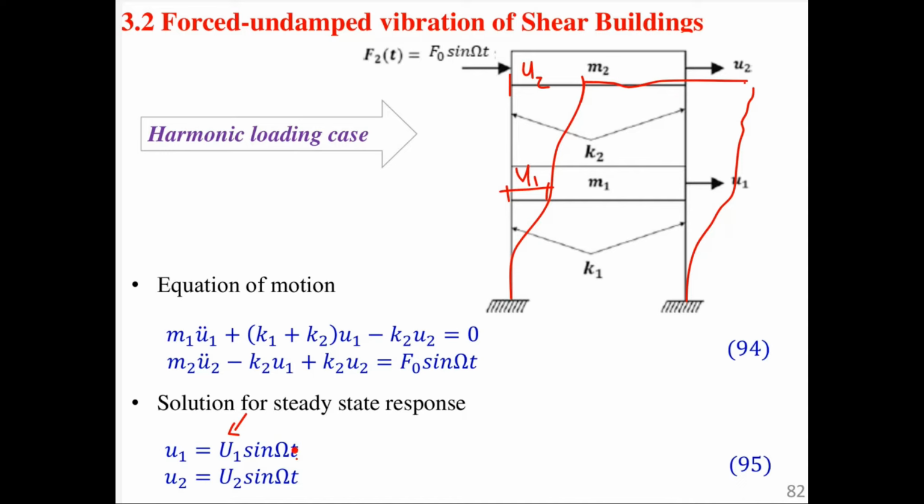So you see at time t0, without even knowing the U1, because this collapses to 0, the structure is still at rest. So what needs to be evaluated is the amplitude of our motion or solution, and then we'll be able to calculate. We have an equation that can express the displacement at the second floor level at a time t equals 5 seconds.